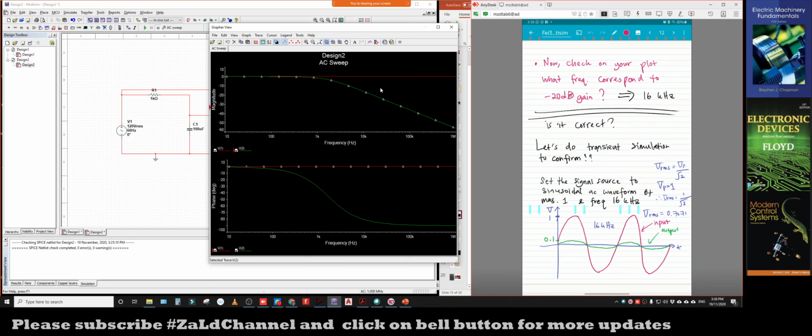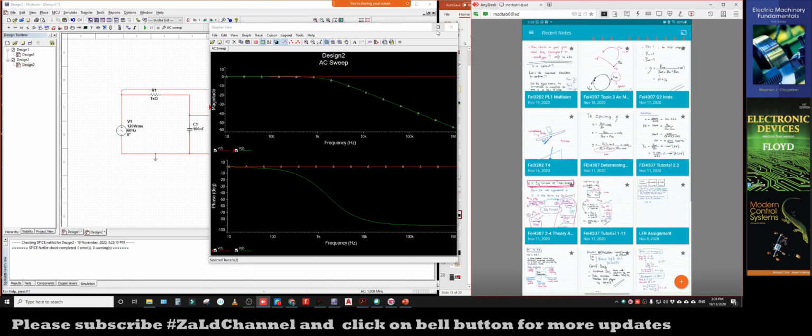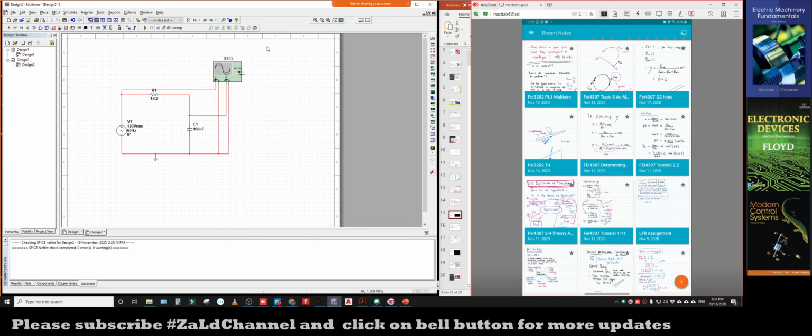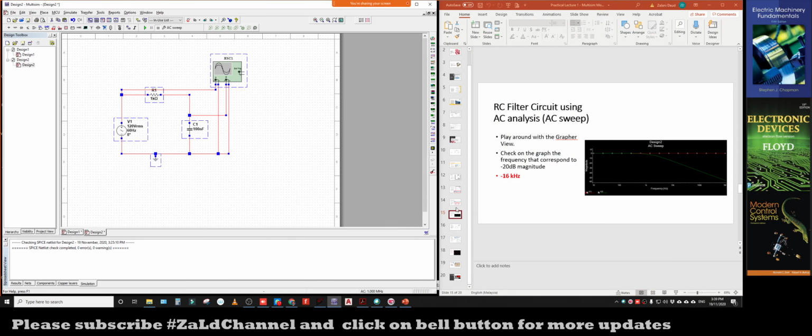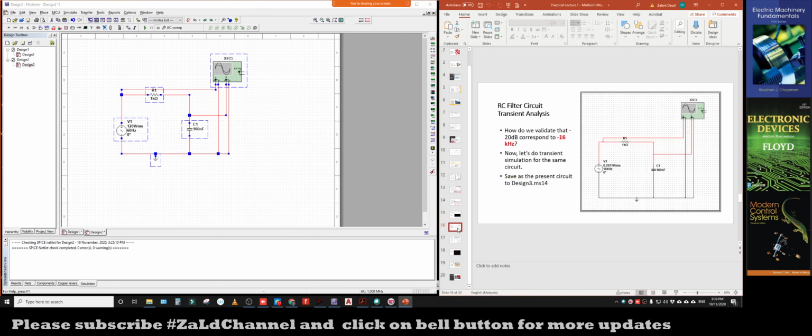So this 16 kilohertz, we can confirm it by further analyzing this circuit using the transient analysis. We resimulate using transient analysis to confirm whether it is correct that negative 20 decibel is 16 kilohertz, for the case where the output is 10 times smaller than the input. So we do the simulation again, and we are going to do the transient analysis.